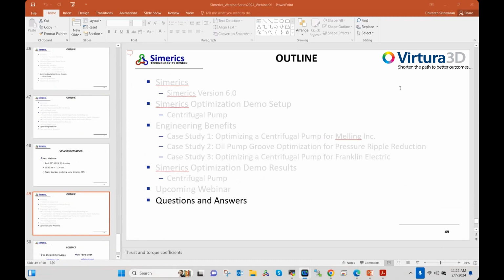From Todd Moser: I'd be interested in how you define the moving mesh for the piston pins and the connecting rods. We have the expression based editor, which is our native scripting, where we write expressions to do some of the moving meshing and squeezing meshing that I showed you. But for the piston pin motion, piston rod motion, and the crankcase, we have already developed something that can be utilized. We don't need to write it from scratch. It's already there. We just need to modify some of the input terms. So if you're interested, please contact me and I'll get you the correct material.